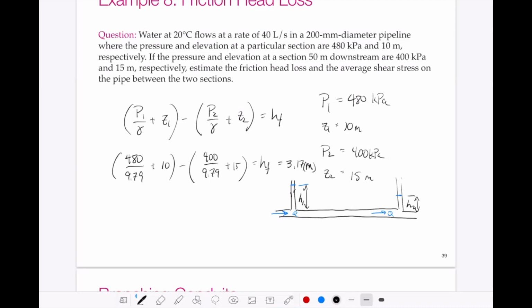So when we talked about pressure head, this is what we're referring to. Just if we had an open tap, we want to visualize this. If we had a bunch of open taps along that flow, the pressure head would be our hydraulic grade line, and that would be changing depending on our pressure and our elevation, and any losses.